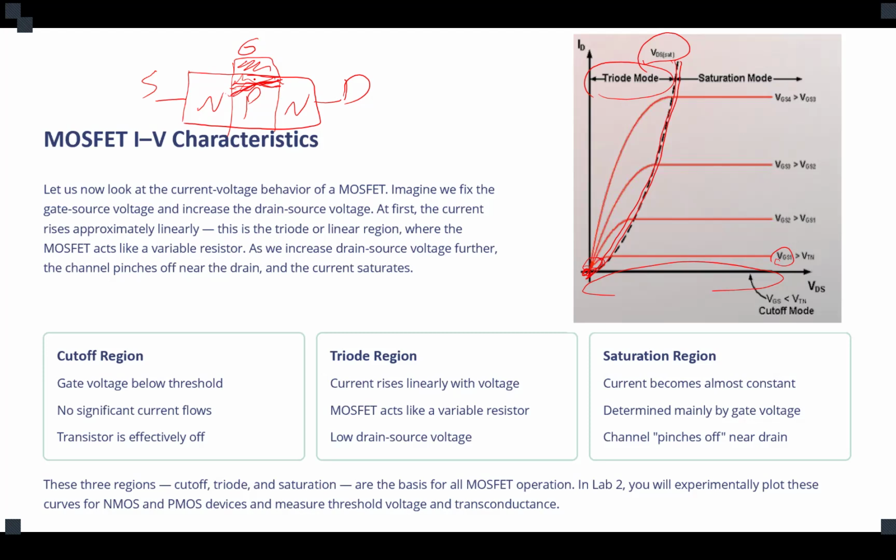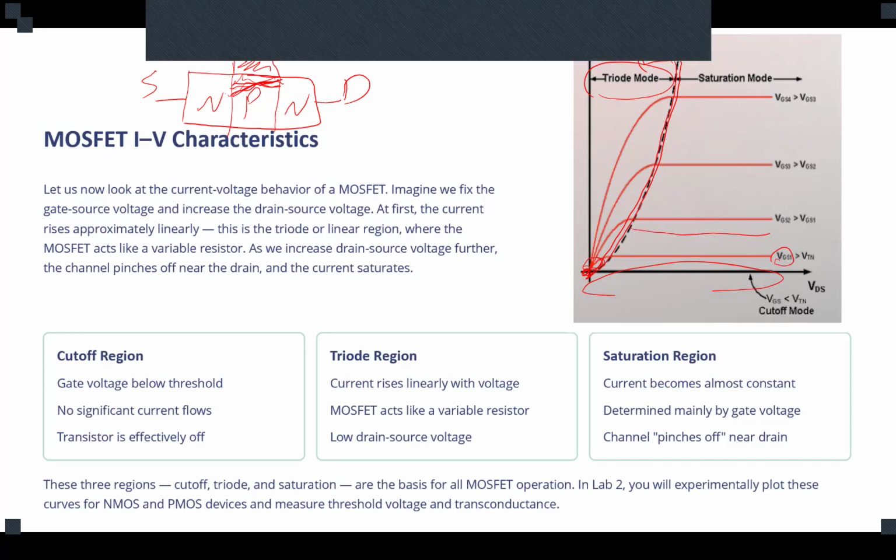So physically, it cannot exceed that amount of current and charge transfer. After that point, when you apply more and more voltage across the drain and source, you still have the same amount of current. So after that, we get to saturation.